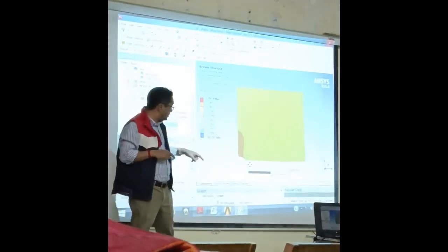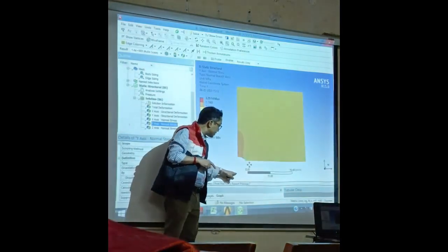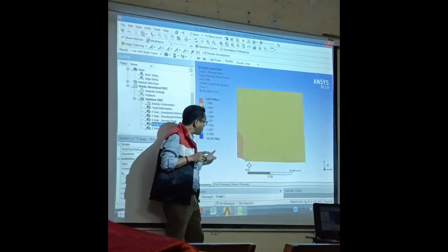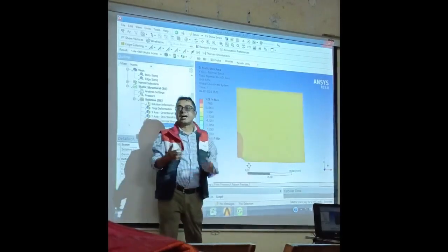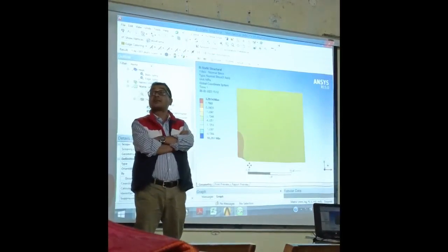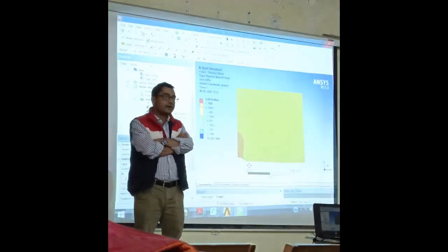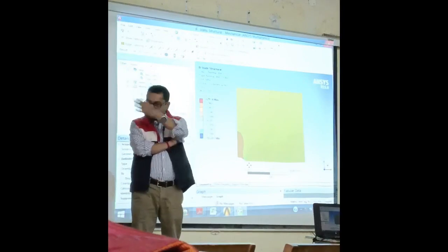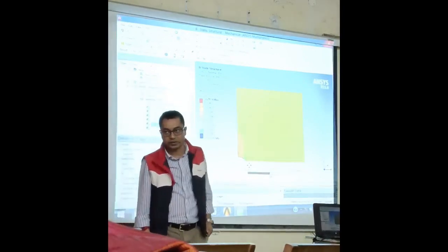Now, the positions, if I have this way, then more disturbance. This load path is not affected. Now, once the load path is being affected by the existence of the cutout, we can get stress accumulated near some edge of the cutout. That is known as the stress concentration effect.